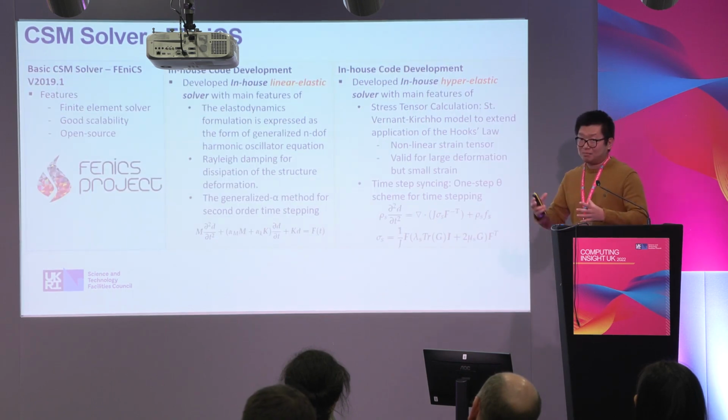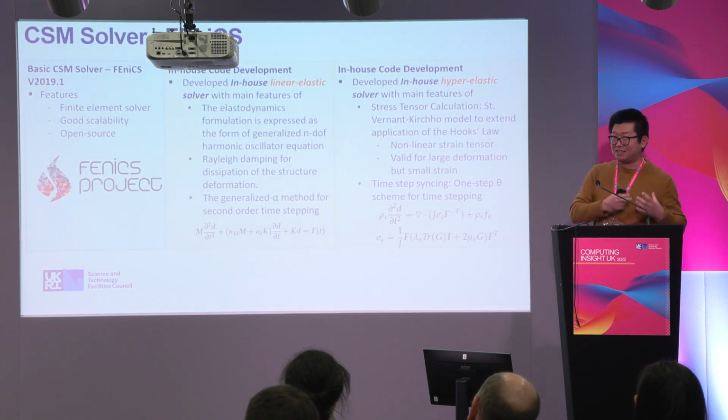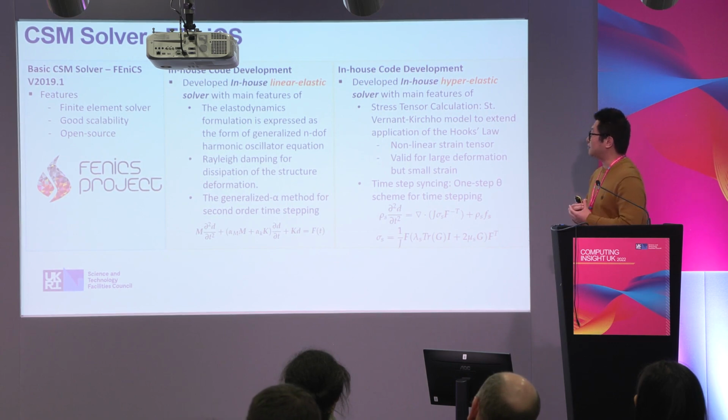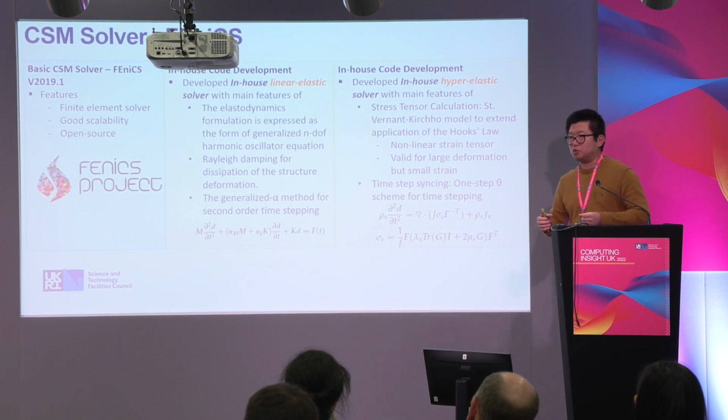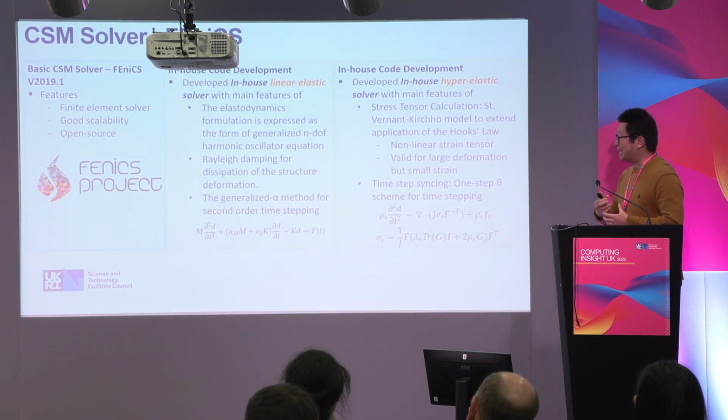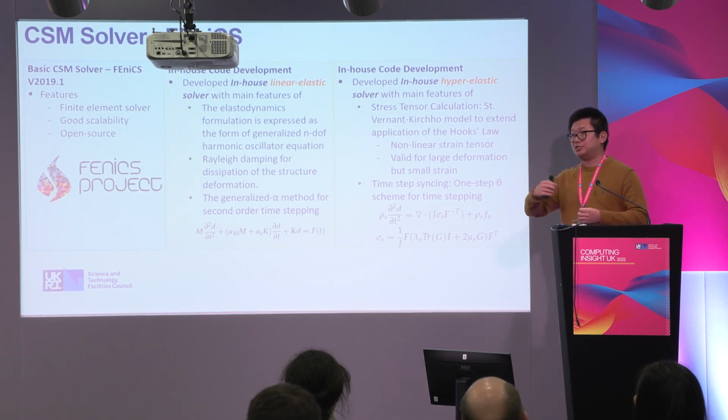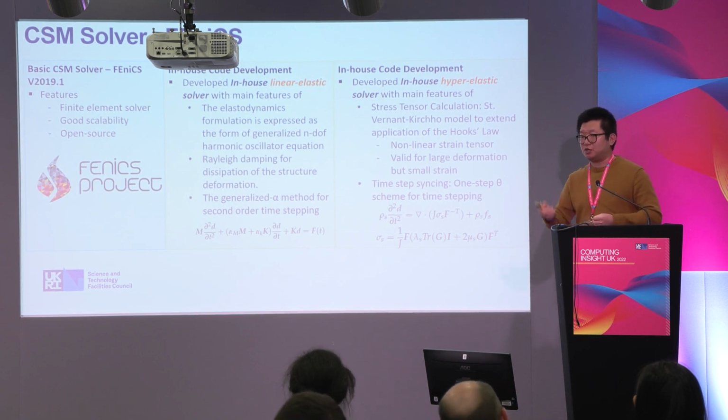For the structure part, on the right-hand side of the flowchart, we use Phoenix, and we have implemented linear elastic and hyperelastic models. The linear elastic model can tackle small deformation with small strain to remain valid. The hyperelastic model can reach large deformation, but still with small strain.